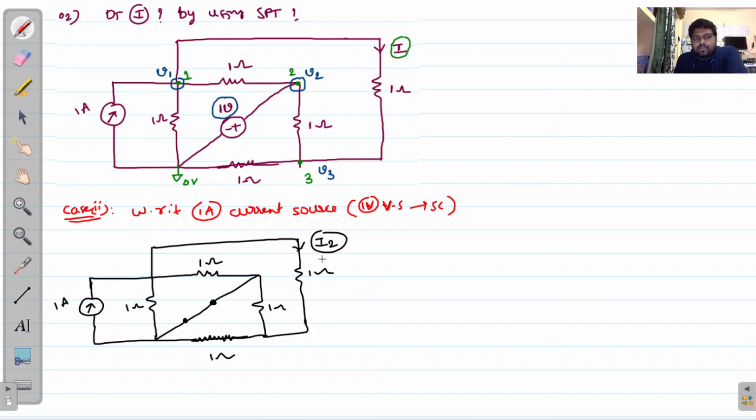Now if you observe this particular point, from this point to this point, this is one complete single path without any element, a complete short circuit, right? If you observe this node and this node, are both the same or not? Why? Because in between these two nodes we don't have any other components. That means we don't have any voltage drop. This entire path has 0 volts voltage drop, so this node and this node are the same. These two are acting as one single node.